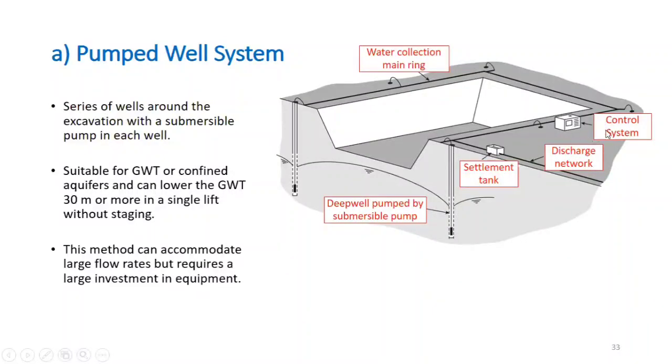And then you need some control system. You need some settling tank where you can allow the sediments to settle, and then you can discharge the remaining clean water into some nearby source. So this system has to keep running for a certain period of time. So that makes it expensive.